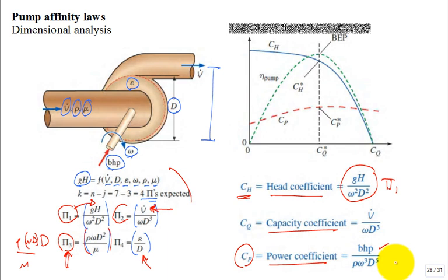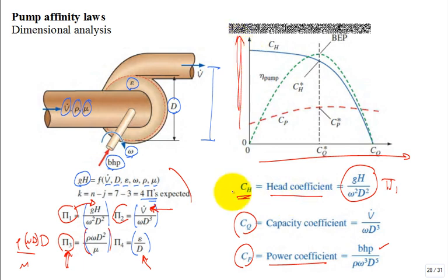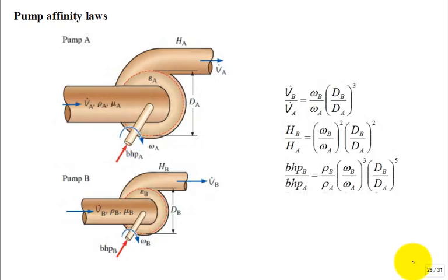And then what you have is you can put dimensionless flow rate instead of physical flow rate with units. So this is the Q sub C, the capacity coefficient. What about this scale? The head coefficient. And so you could plot the head coefficient for that pump as a function of the capacity coefficient. You could then do the power coefficient, C sub P, as a function of the capacity coefficient. And efficiency, you could look and say, hey, they have the same shape. So you develop the affinity laws.